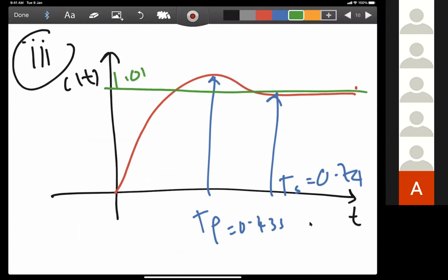So the error state, the ESS, is 0.01. How do you want to overcome the error of 0.01, to become 0? We have to use a PI controller, right? Only then will the ESS from 0.01 become 0.